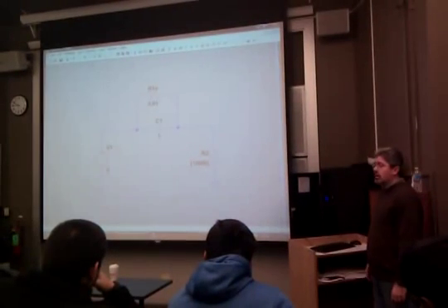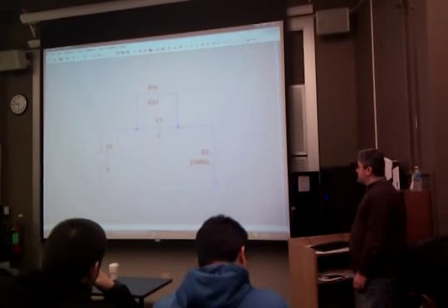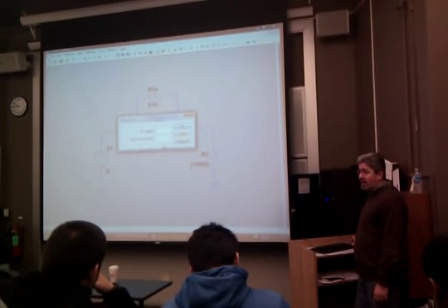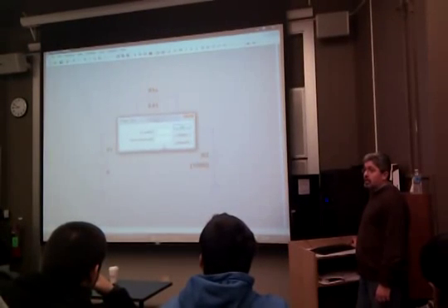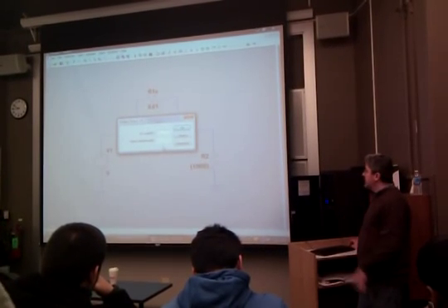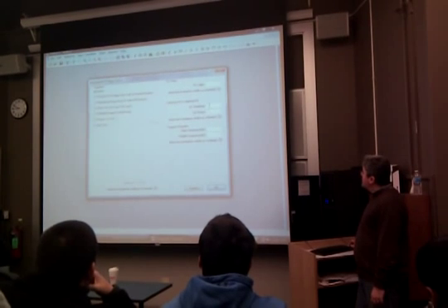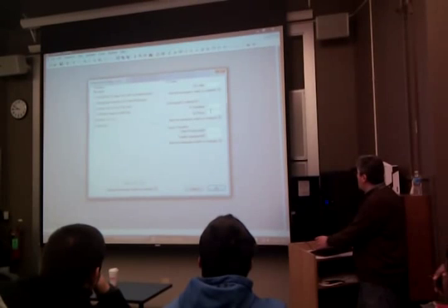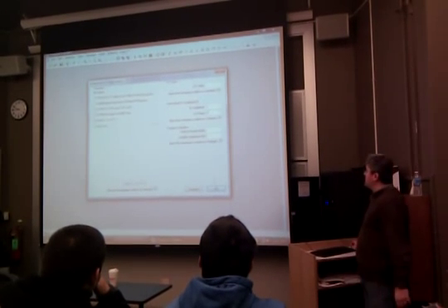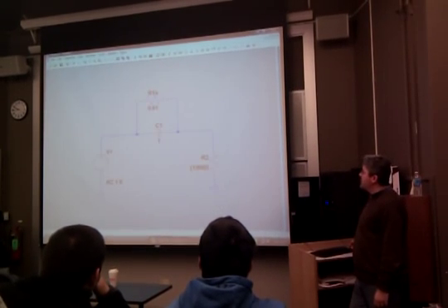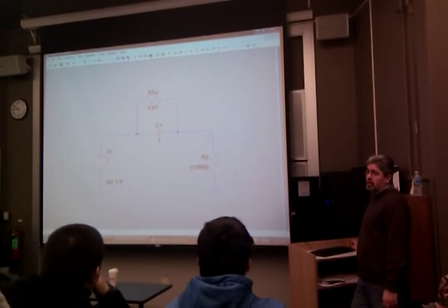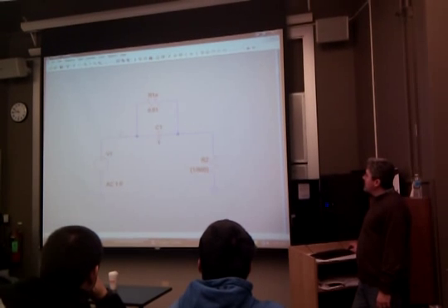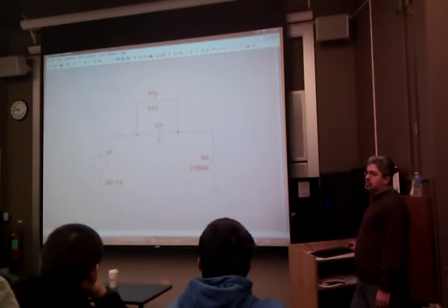You can just leave it in a fraction like that. It's fine. And for AC analysis, you want an AC source. You don't want a sine wave source, actually. You want an AC source, right? Because we're doing phasor analysis here. So you go to advanced, and all you have to do is specify right here amplitude and phase. Amplitude 1, phase 0. We don't care about this because it's all linear. Plus, we're just going to do VR over V anyway. We don't care. Okay?